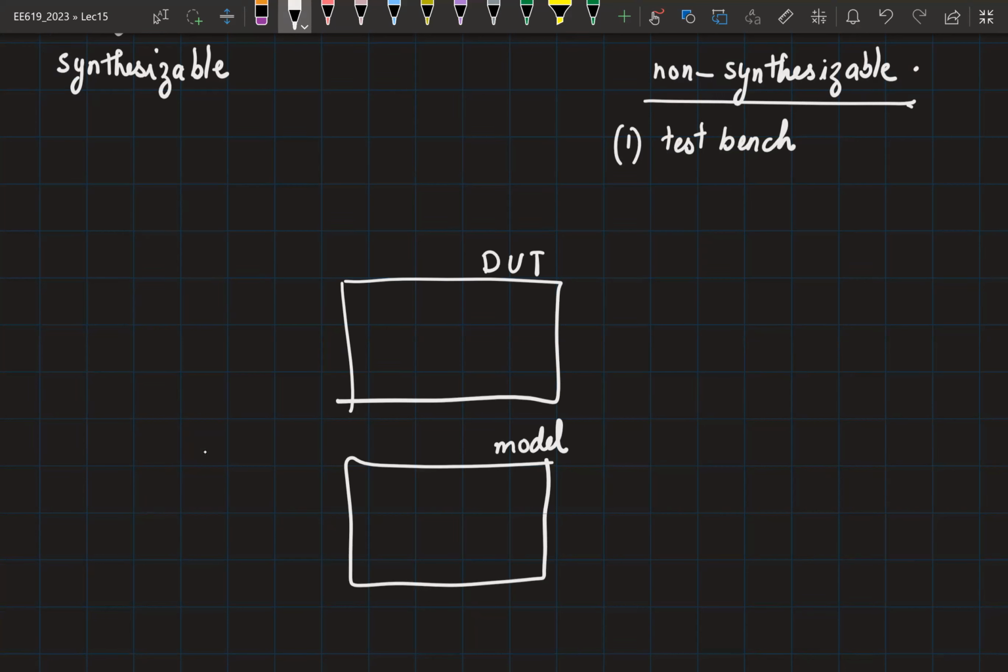This cannot be translated into hardware, but because this is a model, you simply have to look at the input and output behavior. So that gives you a lot more flexibility in describing the behavior. You're not limited to thinking in terms of flops or logic gates, etc. There are a lot more constraints, a lot more commands that you can use for describing its behavior. So this way, you can use non-synthesizable codes for test bench purposes as well as for modeling purposes.